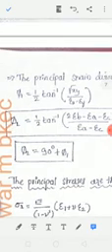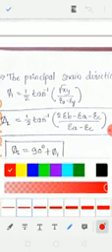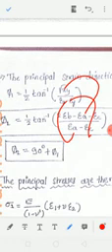Substituting, phi 1 equal to 1 by 2 tan inverse 2 epsilon B minus epsilon A minus epsilon C divided by epsilon A minus epsilon C. So how will you get phi 2? The strain direction equals 90 degree plus phi 1.